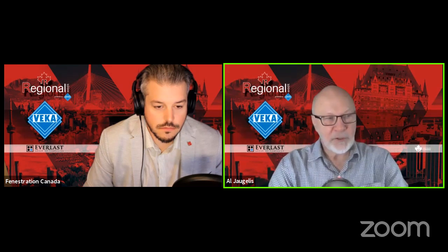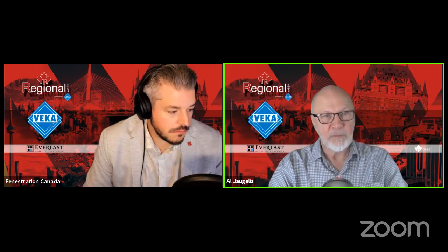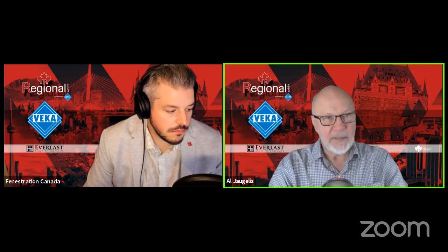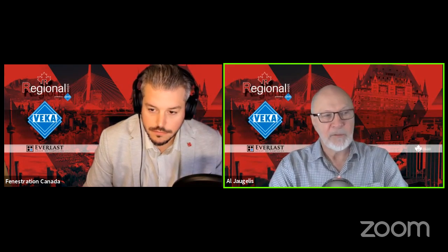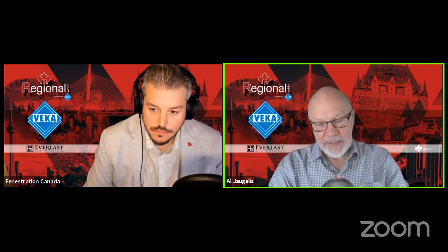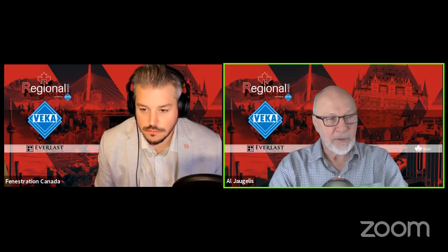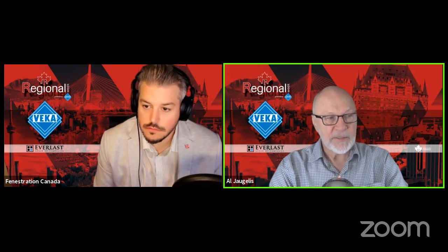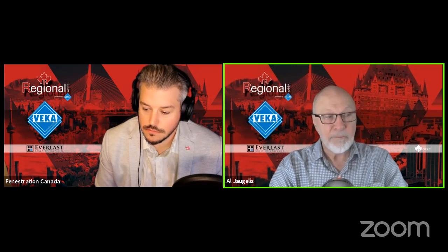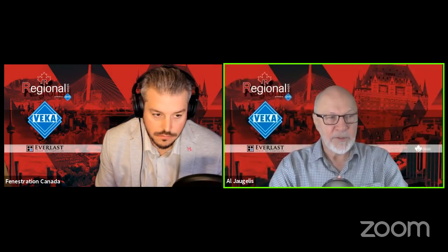simply because before the 2010 National Code, there was almost no regulation at all of the wind pressure of windows, and those windows are not failing in service. They're not blowing out from the normal winds. Then again, we are entering a period of climate change where we are having increasingly frequent storm events with much higher wind pressures than we've had historically. So I think this is really a question for the local building authorities to address.